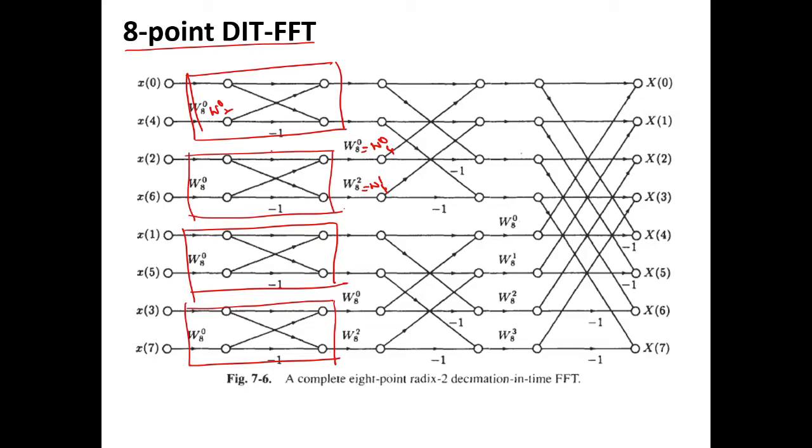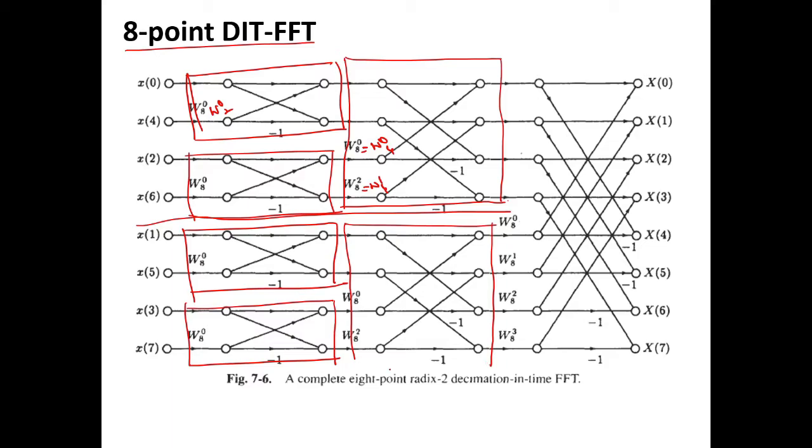Now, after that, if you remember, we performed 4-point DFT. We will be doing the same thing here also. Over there we said that this is the middle point, and this is 1 2, again 1 2. Same over here, 1 2, 1 2 out of the middle point. Now we have to do the same for the 8 points in the final stage of an 8-point DFT or FFT. So which is our middle point? Our middle point is here.